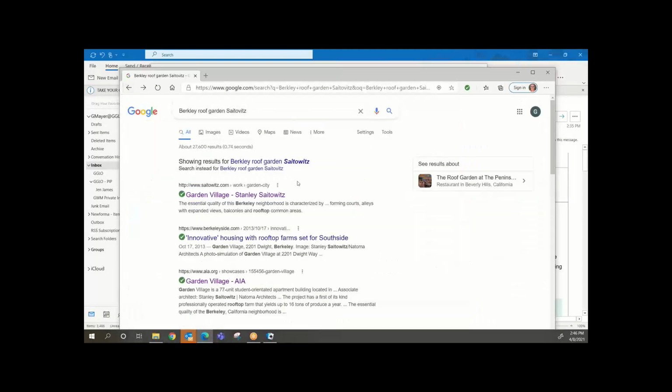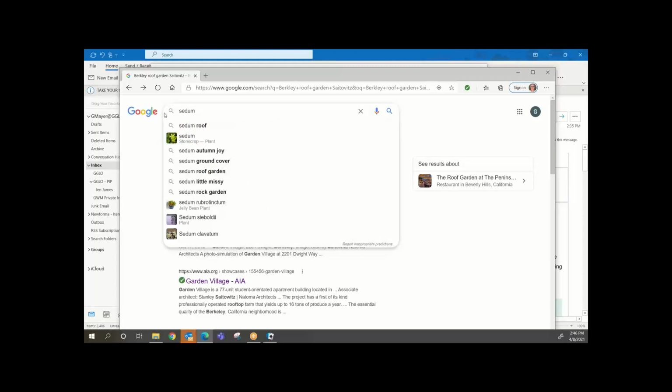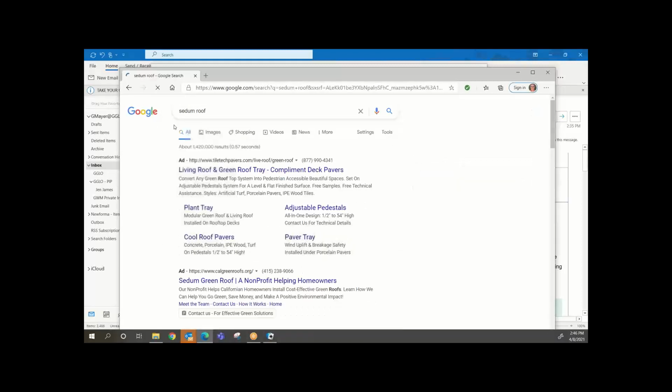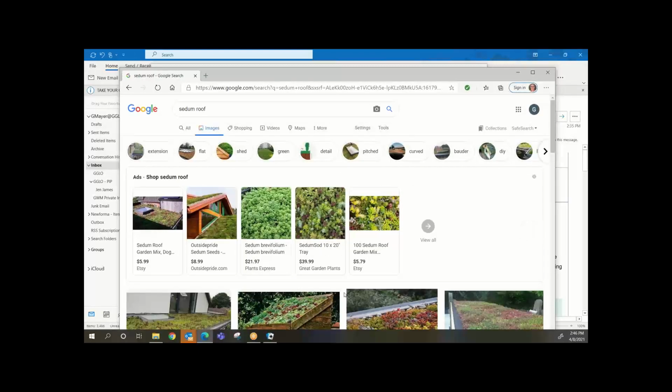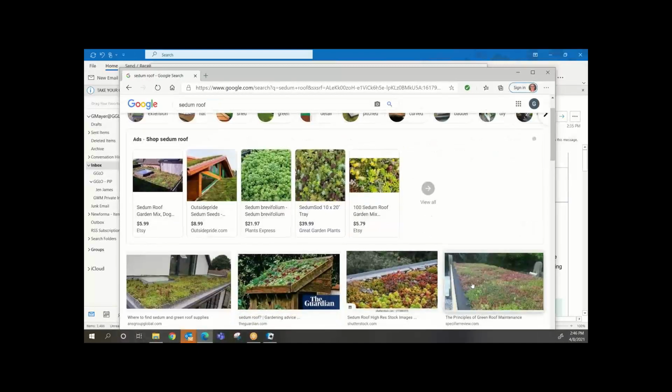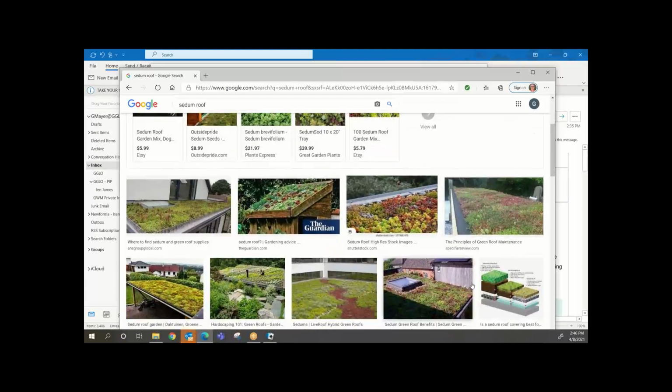And then you just have a mechanical roof, but it has absorbability for rain events. And it just has some sedum on it. You know what sedum is? No. Sedum is a very low maintenance plant. So you got roof gardens, roof parks, and roof solar. This is basically a plant that you never have to do anything with. There are evergreen succulents and stuff up there that live forever. So this is pretty much baseline, a contribution to the environment kind of roof. And it protects the membrane so the roof actually lasts longer. But this is not a usable roof.